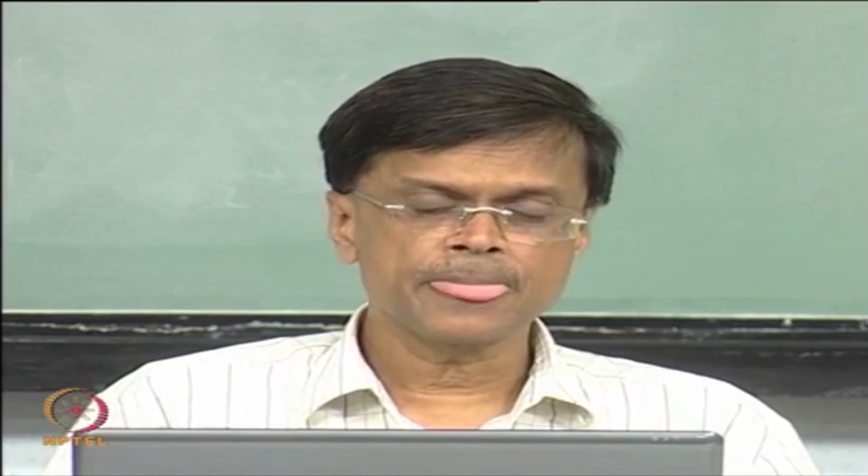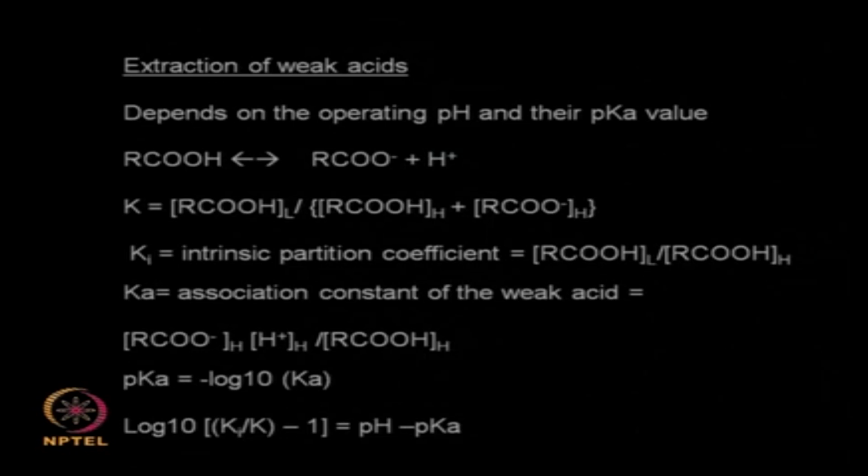The main disadvantage of cross flow is every time you have to add a fresh solvent, that means the solvent usage is going to be very high, whereas in the counter current design the solvent which is leaving stage 1 will enter stage 2, that way you are not using too much solvent unlike the cross flow design. And the equations for the counter current design change when compared to your cross flow design, we will look at it later, but before that we will look at something else.